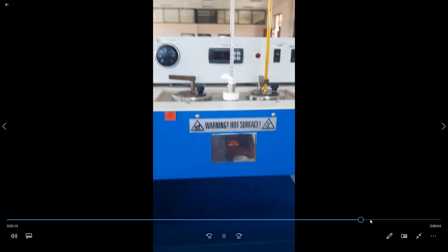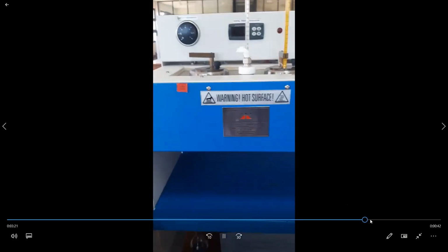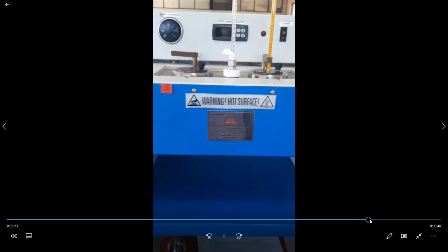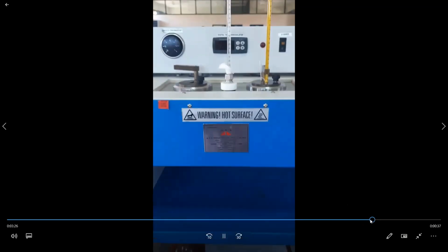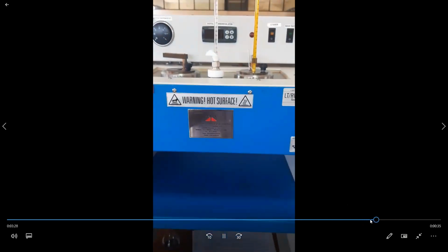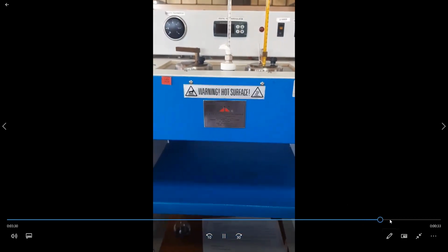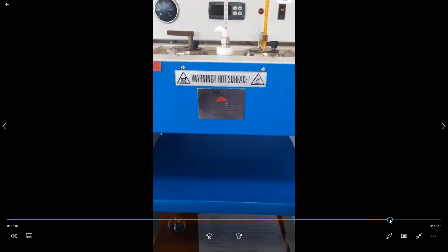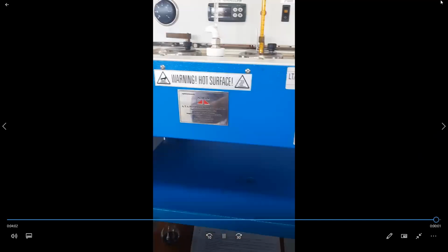So now we will heat up to some degrees Celsius, then we will collect 50 milliliters of oil sample and measure the time for 50 milliliters to flow through that orifice. This is in the lab sheet.